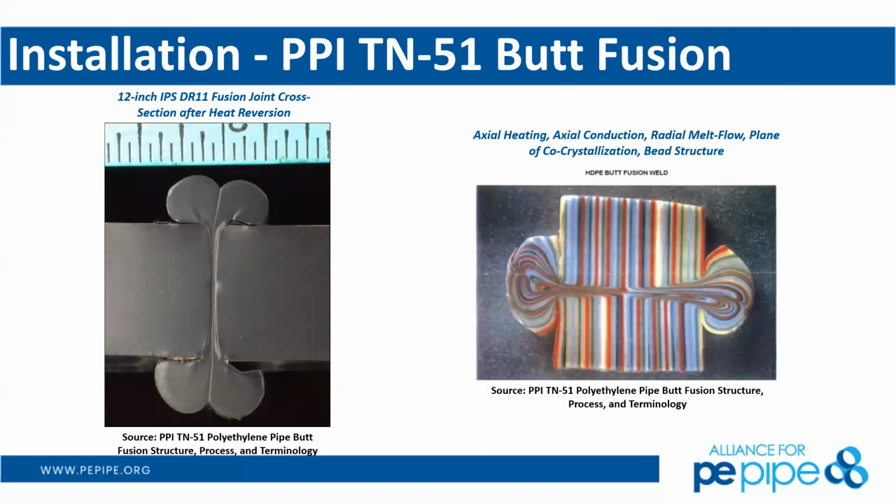Now, it's very important to know the bead does not really affect flow. I know some people want to go in there and take that bead out. The C factor of 155 for polyethylene includes that bead and is not a problem. The joining method is in that wall thickness.